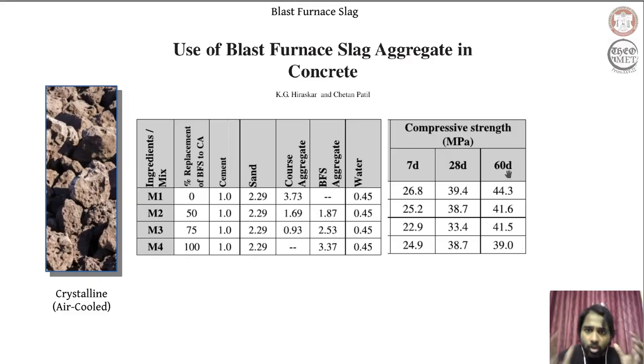So the concrete with 2 different compositions of slag and aggregate gives us almost equal compressive strength. Now when we compare that compressive strength to that of pure concrete with exclusive aggregate, with no traces of blast furnace slag, we find that the strength is not significantly different, it is comparable.